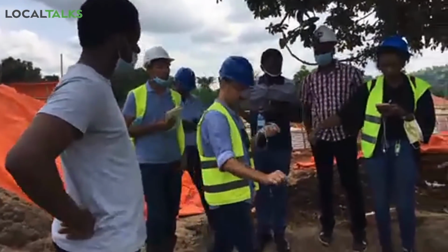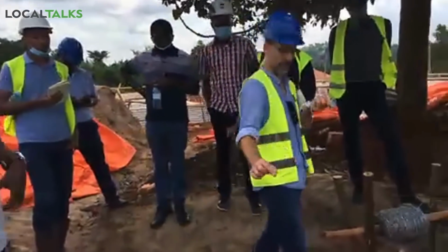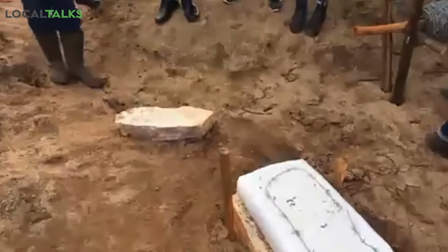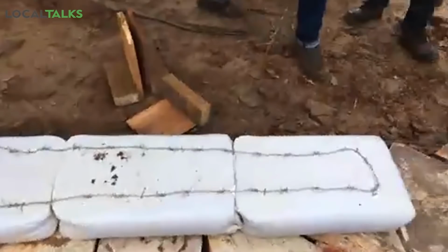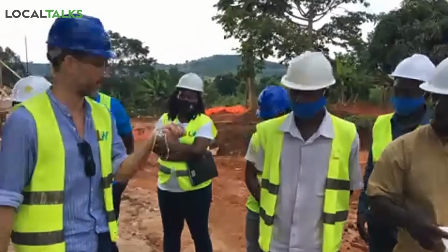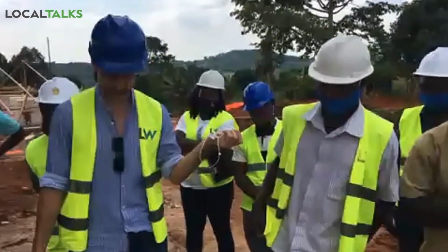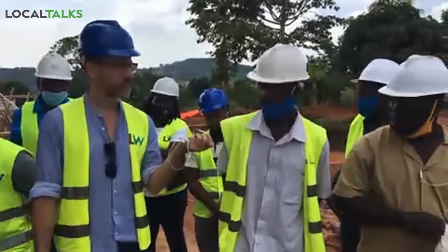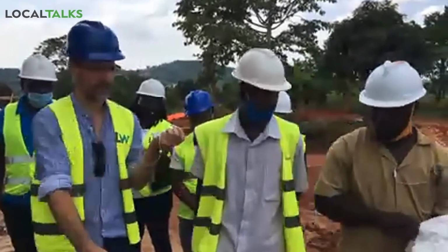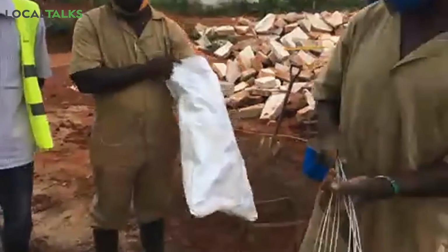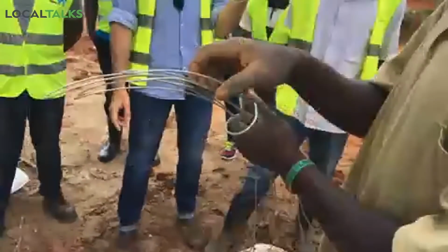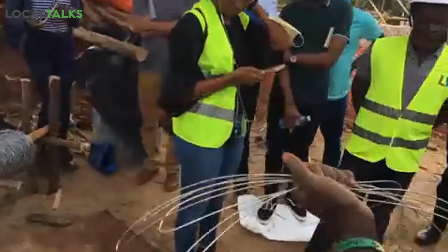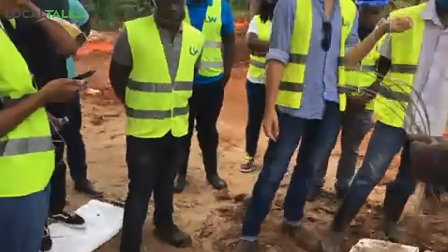Geoffrey, under normal circumstances you would have also fitted your binding wires now, in order to later help us with the plaster? Yeah, we are supposed to put wires which can help us when we are plastering. You have them here? Yeah, they're coming. Wonderful. What spacing do you use in length? I think we are using 400. Every 400. Okay.